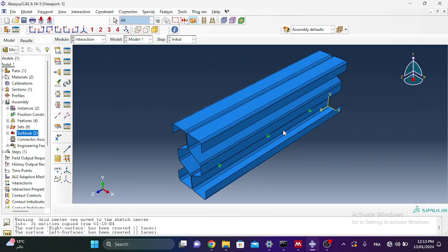Here you can continue your operation by introducing the boundary conditions, the forces, and you will see the deformed shape, and the connection between your surfaces is very accurate. You have only to know one thing, that this method is only used when there is no damage happening in your screws before reaching the ultimate stress. If the damage in your screws happens before that, you can't use this method.